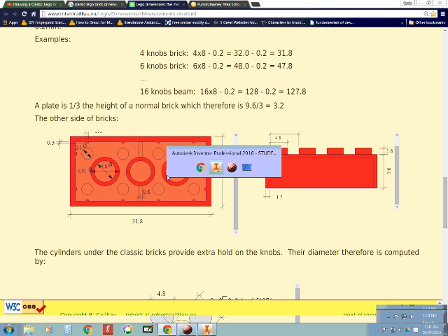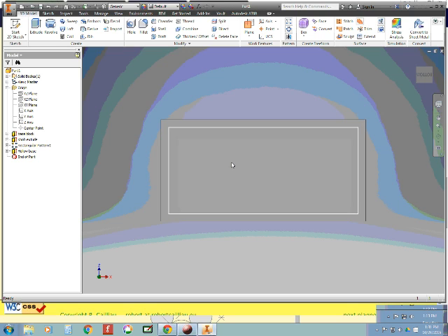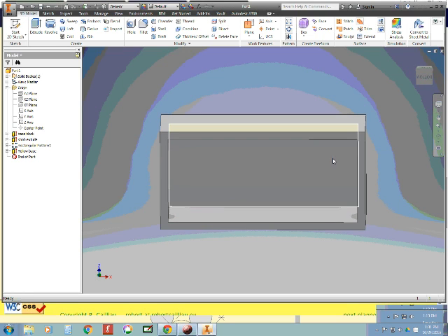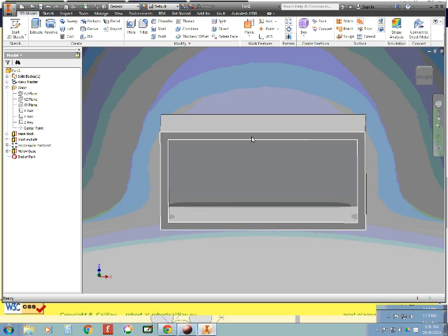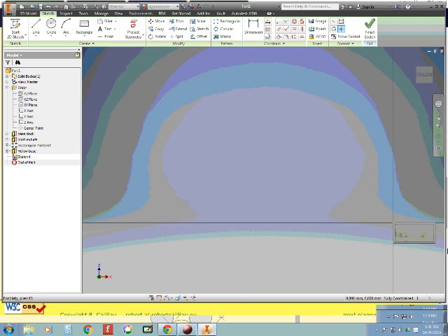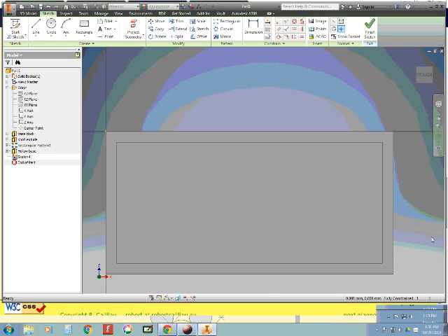That's these. This surface right here is going to be the surface we draw on, and then we're going to extrude toward us. So again, if you right click and choose New Sketch, it picks the surface that you click on as the surface where your sketch is created.